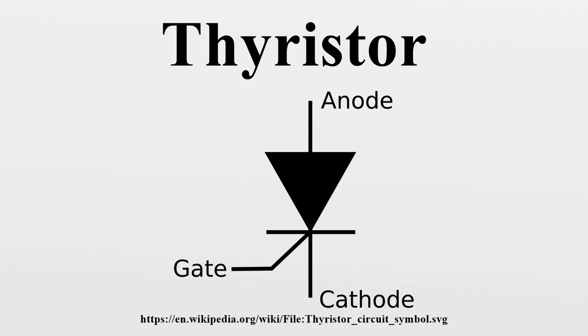One major problem associated with SCRs is that they are not fully controllable switches. The GTO thyristor and IGCT are 2 devices related to the thyristor that address this problem. In high-frequency applications, thyristors are poor candidates due to large switching times arising from bipolar conduction. MOSFETs, on the other hand, have much faster switching capability because of their unipolar conduction.